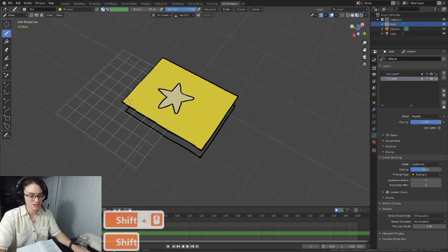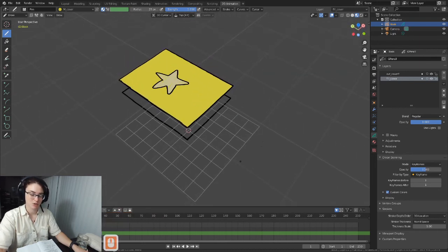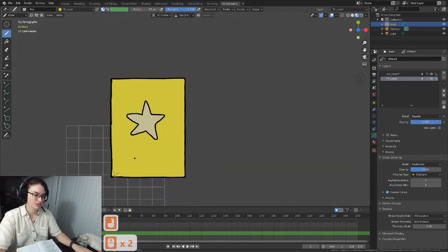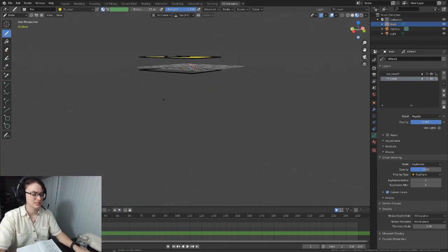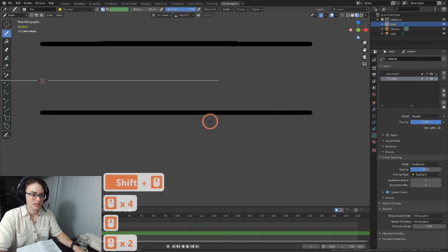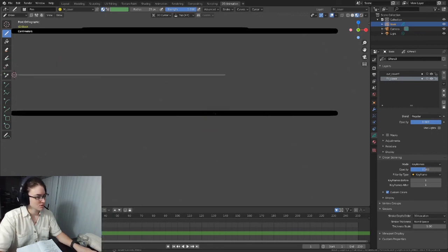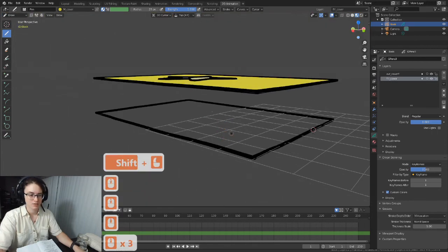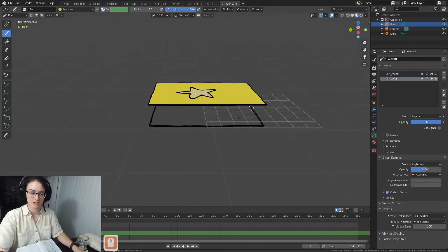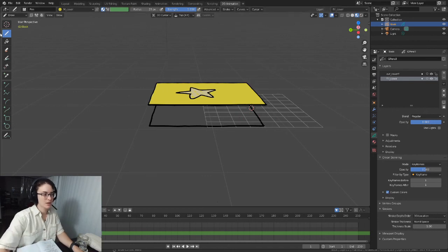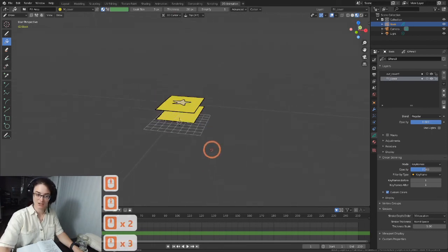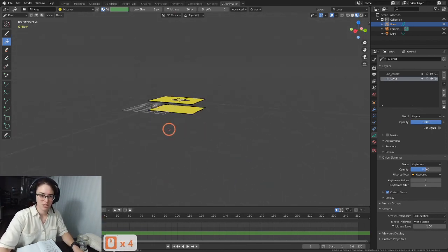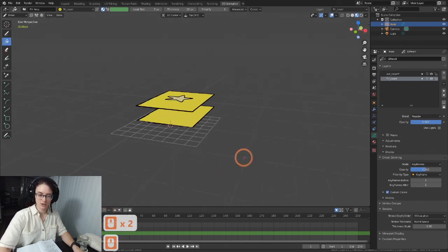Again, we're going to have the same issue here because we're in a 3D space. We can't really see the depth we're putting it at. So let's go into our orthographic. And actually, I don't want to be in top view. I want to be in a side view so I can get it down at that level. So front or side. And then I can Shift right click right down here. It's okay that it's not centered on this because that's just showing the plane I'm in. So now if I hit my little dump bucket, you can see it's going in the correct area. Beautiful.